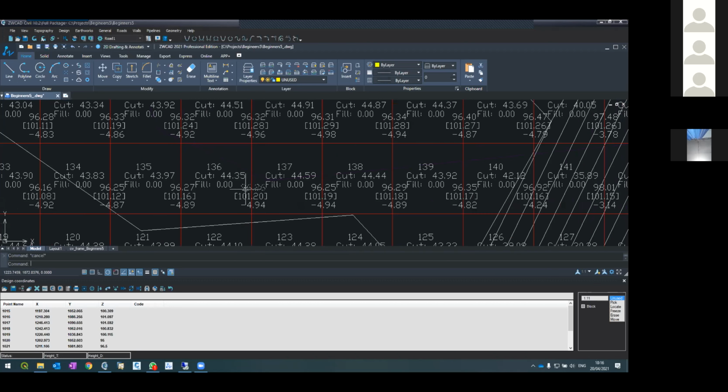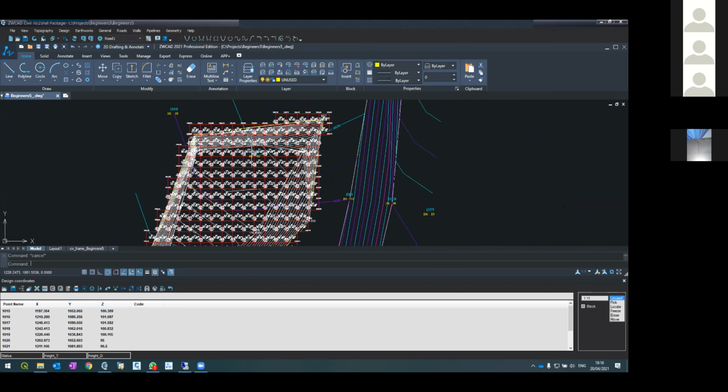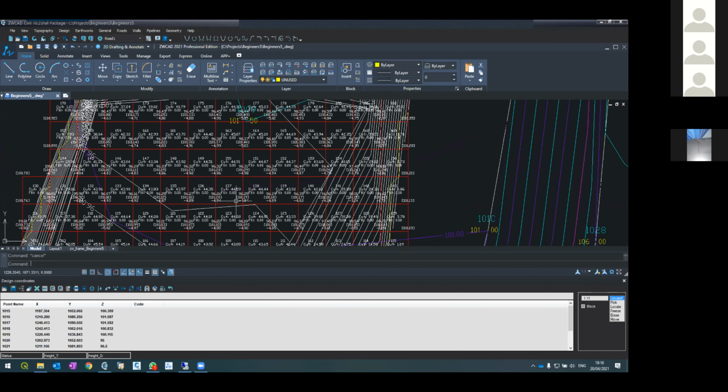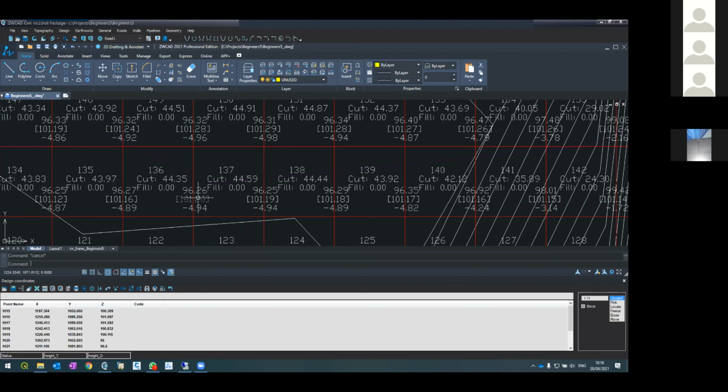You see, this is the elevation in the pit. This is the topography, which was from the first surface, the one before we did the pit. And then the difference between them gives us a number. So it means here, at this point, they cut 4.94 meters deep inside. This is the depth of the pit.